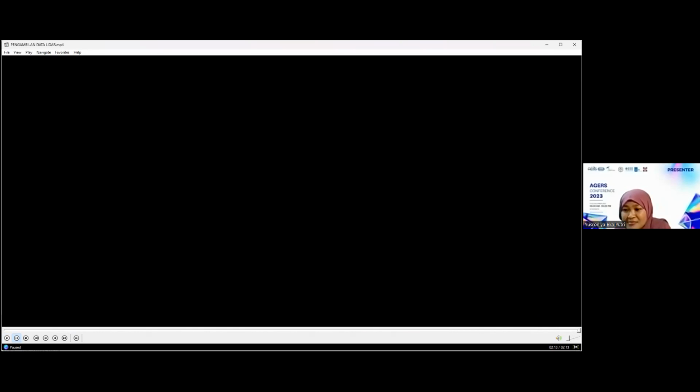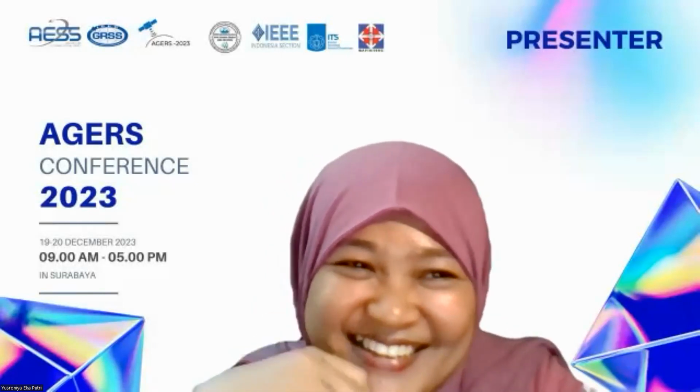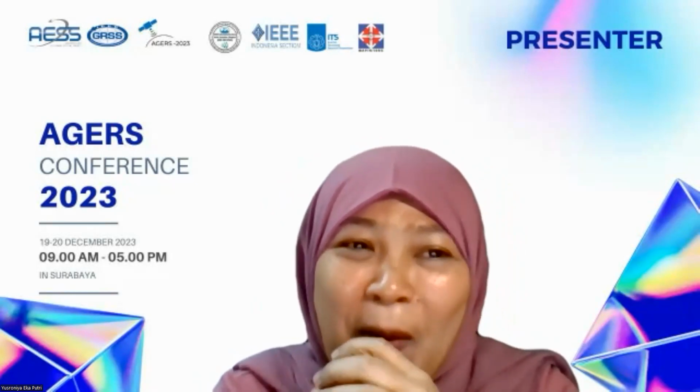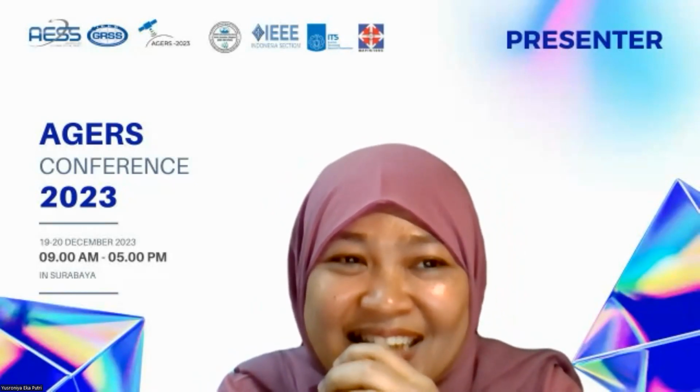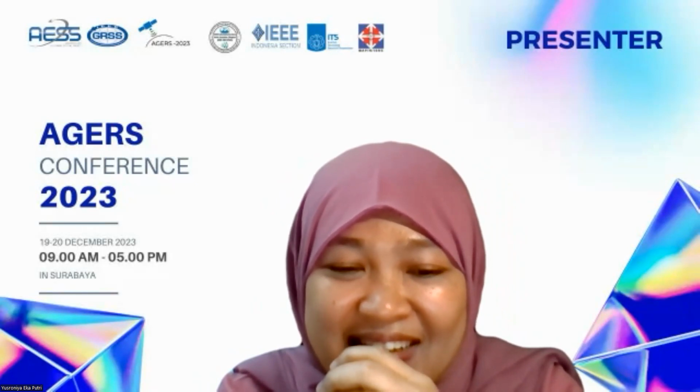About the video, I think it's quite strange, because the antenna height that you use is lower than the head of the operator. If geodetic people see that kind of measurement technique, I think it becomes a problem for you. The antenna should be higher than the operator's head. Okay, this is just a comment. About the coverage, I would like to know. Thank you.